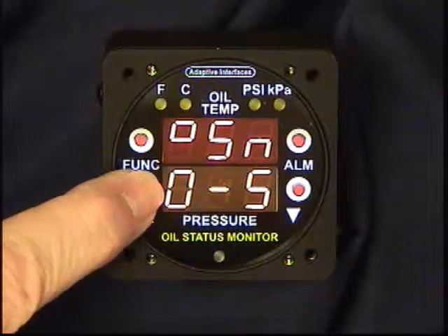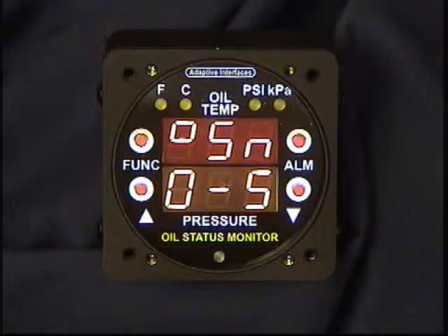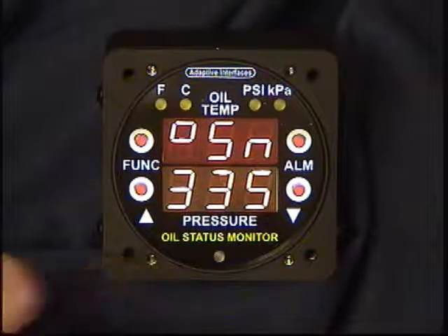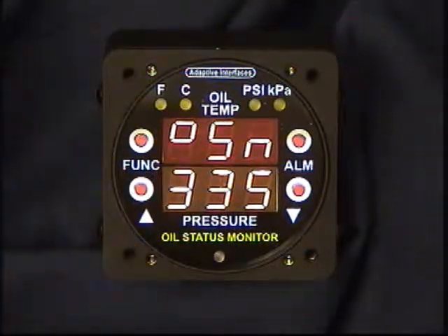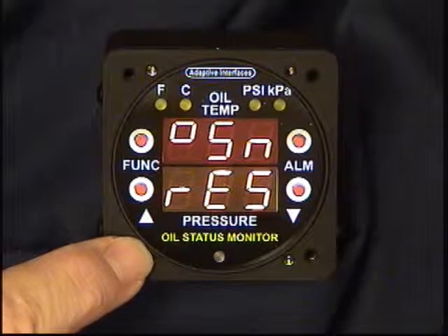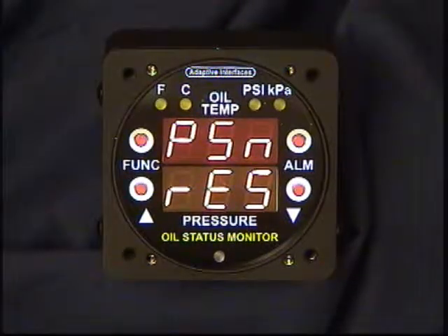The next type of sensor is an electronic sensor that provides an output of 0 to 5 volts depending on the temperature it's reading. And the third type of sensor is an LM335, which is a common solid state type temperature sensor. And again, the instrument can be selected for one of those three types. Right now we're going to leave it in the resistive sensor mode or selection. And we'll go over to the next function,